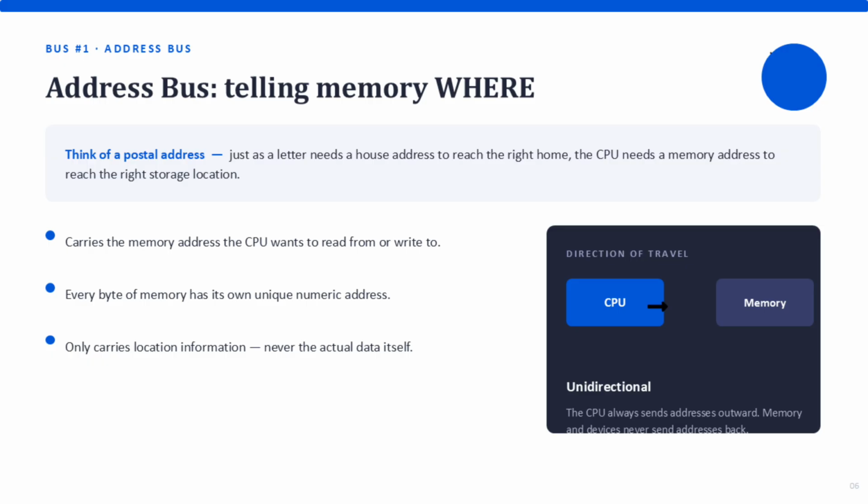Notice something very important. It does not carry the actual data. Many beginners confuse the address bus with the data bus, but they perform completely different tasks. The address bus simply points to the location where the data is stored. The actual information will travel later through the data bus. You can think of it like writing an address on an envelope. The address tells the postal service where to deliver the letter, but the address itself is not the letter. Similarly, the address bus tells memory where the CPU wants to access information, but it does not carry the information itself.